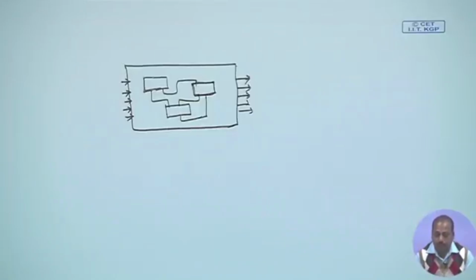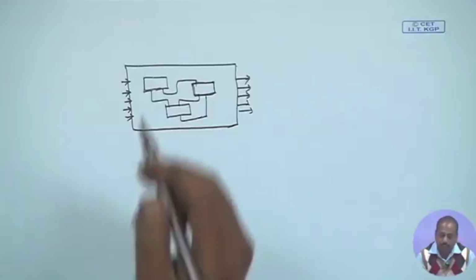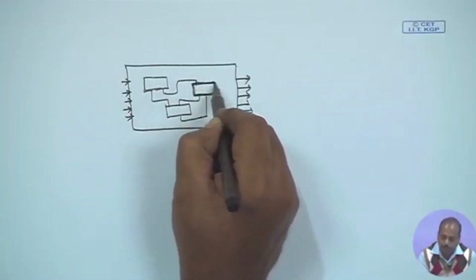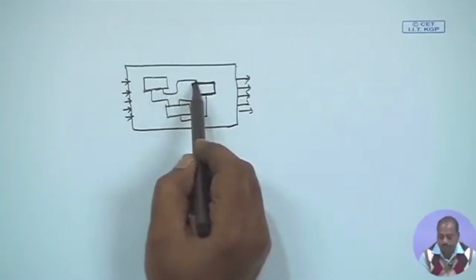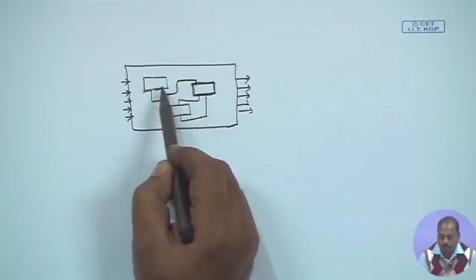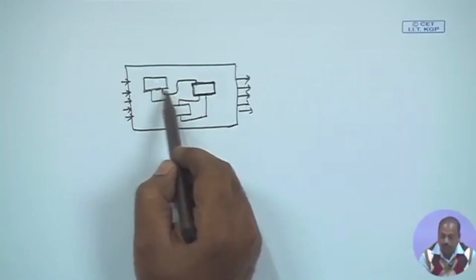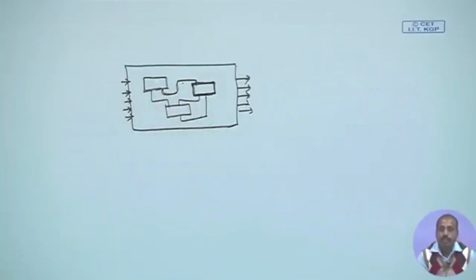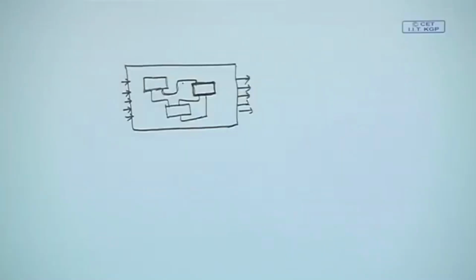So, for that purpose, without picking the chip out of the slot, if we want to test it, then we have to apply some test pattern to this chip. Now, since this signal line is coming from here, I need to make this chip operate in such a fashion that the desired output comes at this point, and that is a very cumbersome process, because chips are not as simple as individual logic gates. At a circuit level we could try to do a justification using some ATPG algorithm, to justify how this line can be made 0 or 1, but at a board level that is not possible.